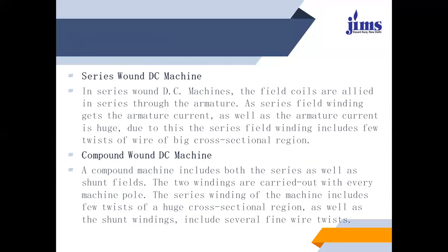But in the case of the series field winding, as the armature current is very huge, the same current flows through the field winding. So we require a smaller number of turns, but the size of the wire will be larger.